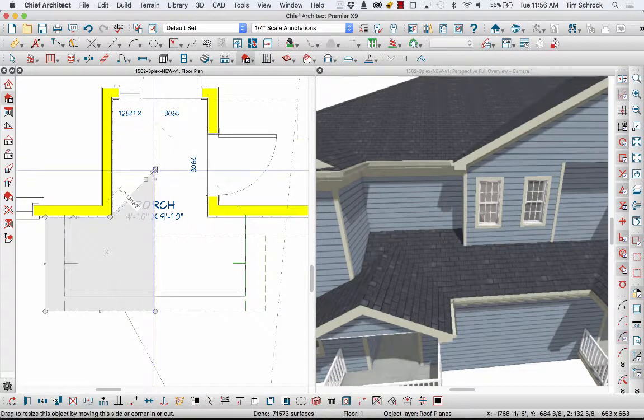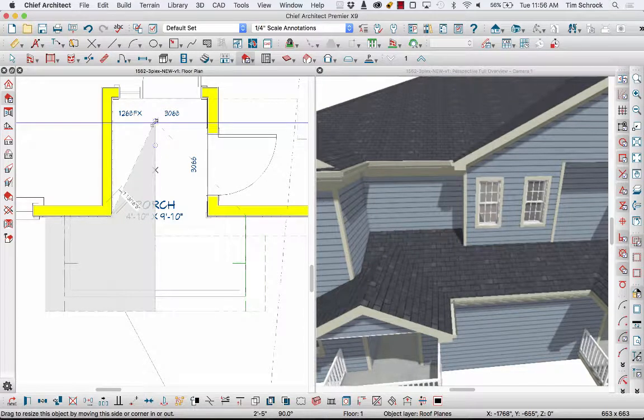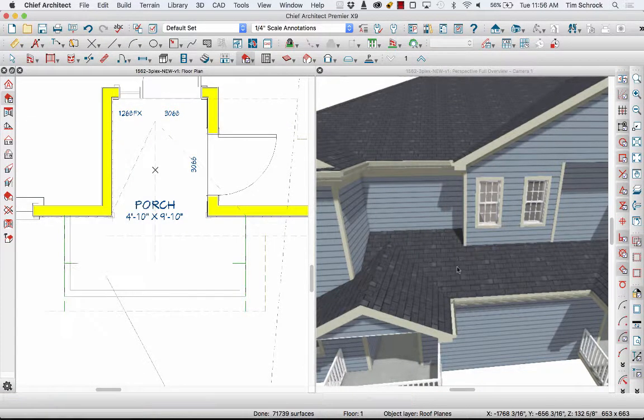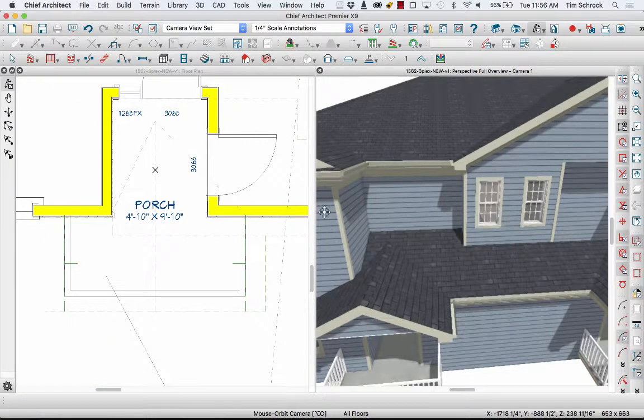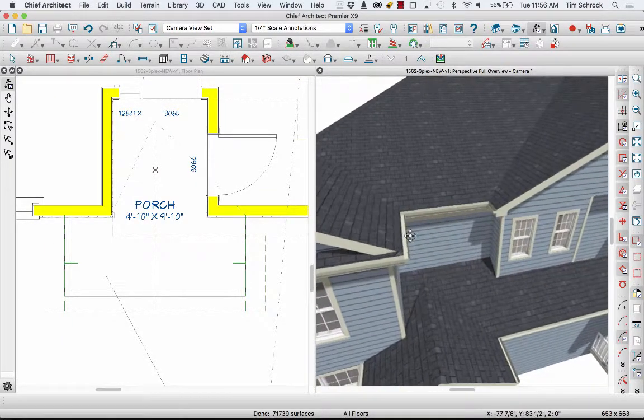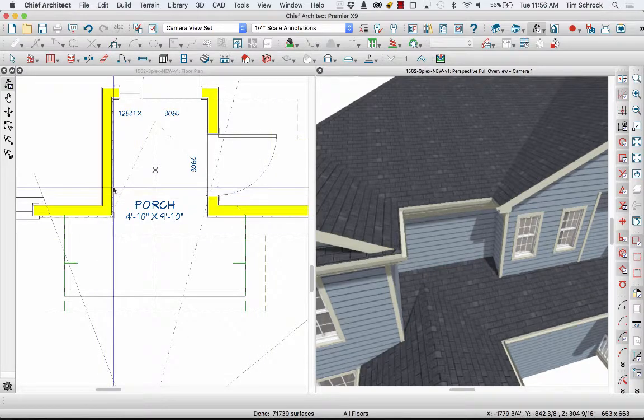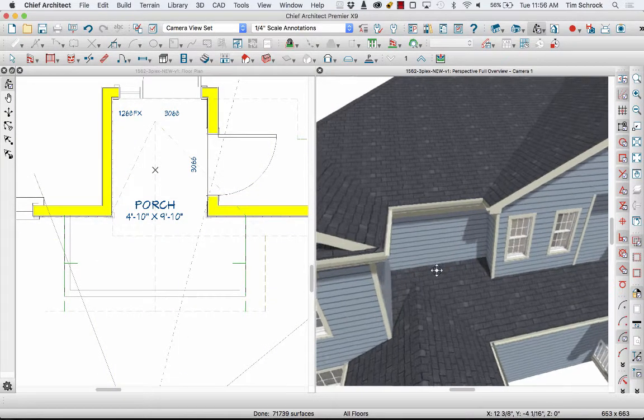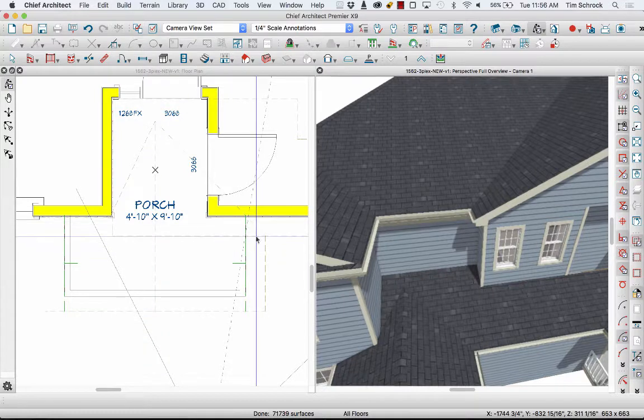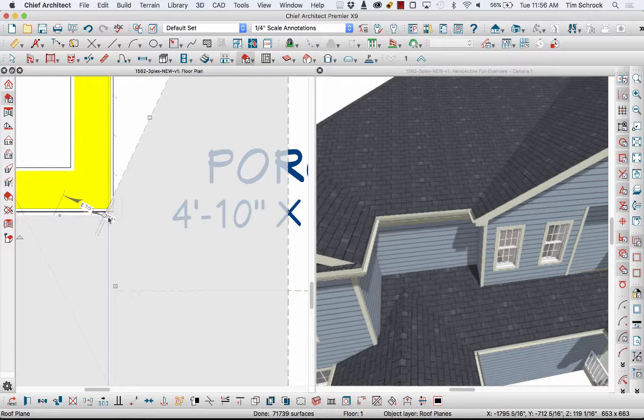I'm going to select the left edge of left plane of this gable. I'm going to change the perspective of this so we can see what's happening. So far so good. I just need a little cricket in here because this is not watertight yet. Once again, I'm going to select this gable, this plane of this gable, and move that out to the edge of the siding.